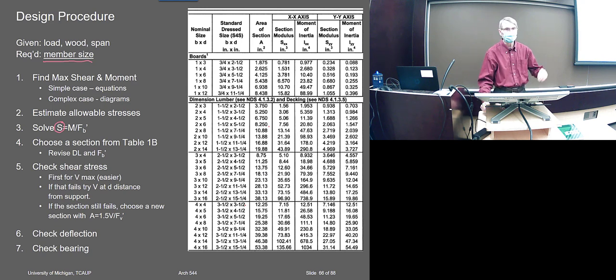When you do this in steel, because you've got so many shapes, they actually give you a table set in order of the section moduli, right? So you can start at the bottom and just go up, and they even group them in nice little groups. There are not that many options in wood, so it's not really worth making a table like that. So they just put them in here, and you can just come through this and pick one out.